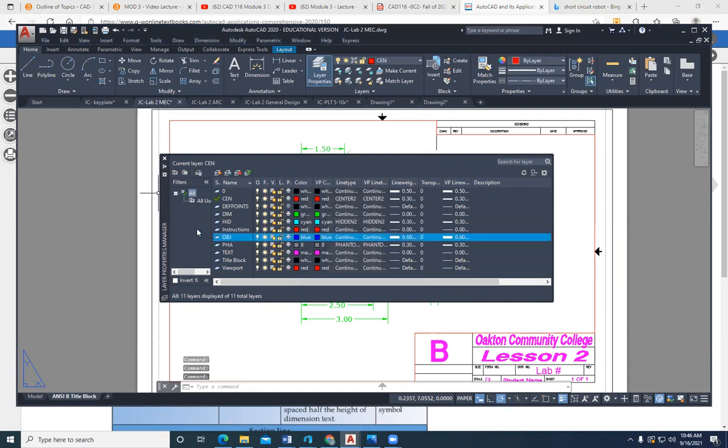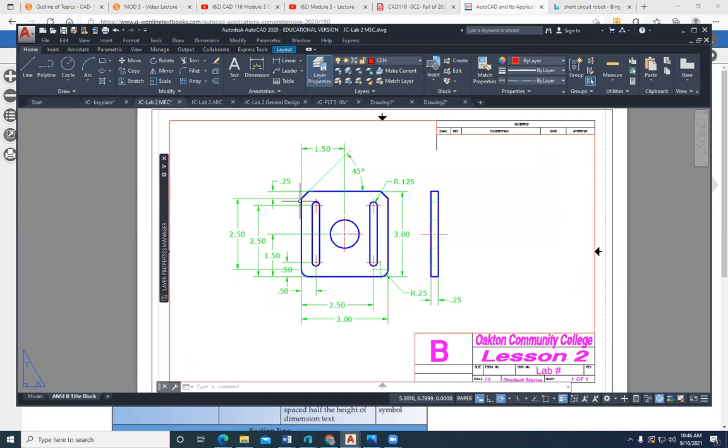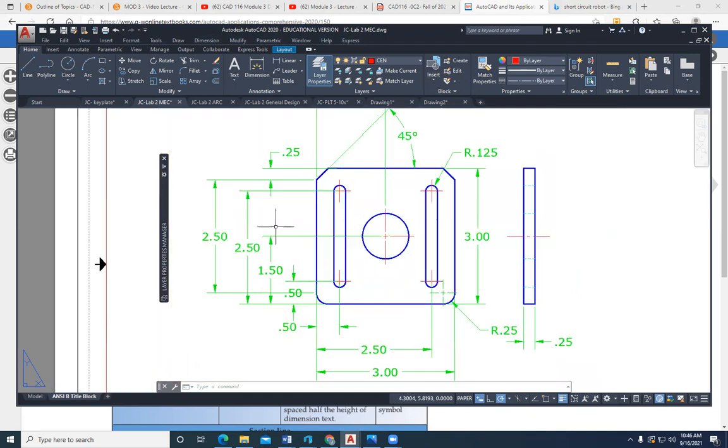You're not going to see a noticeable difference. And then here's my hidden lines. These are 0.3 millimeters for the line weight. Because as you make these drawings, your eye will catch the thicker line weights first. And you can kind of see that.